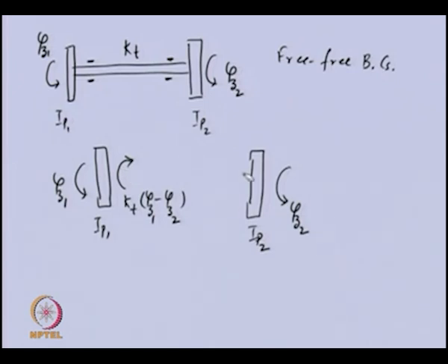That will be the same, because this is the torque which is transmitted from the shaft, but it will be acting opposite to that. That means, if we have a free body diagram of the shaft, this torque will produce a reaction here, which is in the clockwise direction.